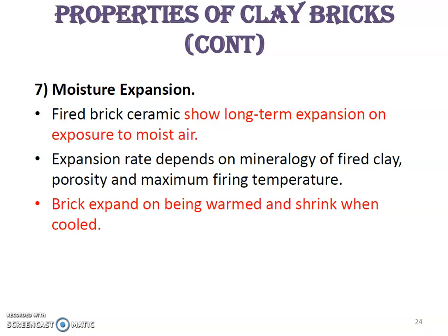Okay, then is moisture expansion. Fired brick ceramic shows long-term expansion on exposure to moist air. So this means that ceramics expand when there is moist air. However, other types of brick will expand on being warm and shrink when cool. The expansion rate actually depends on the mineralogy of the fired clay, porosity as well as maximum firing temperature.